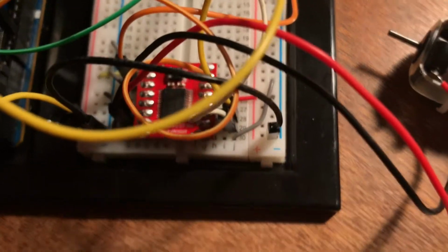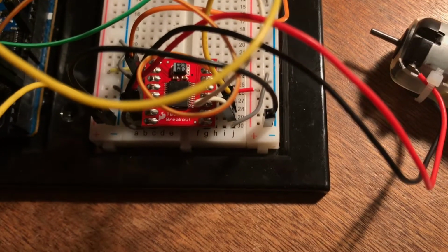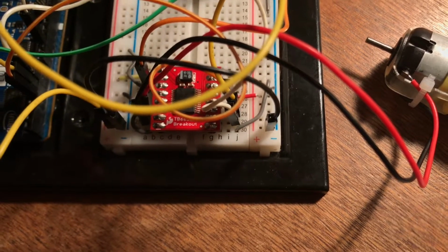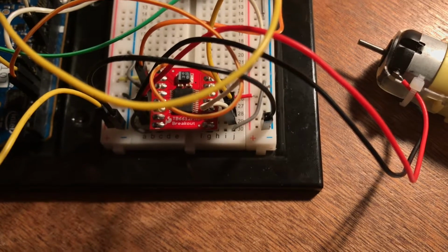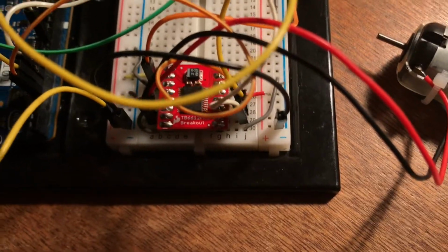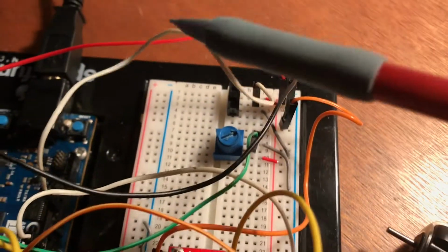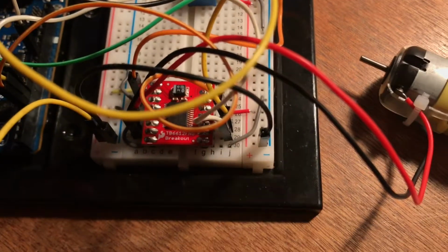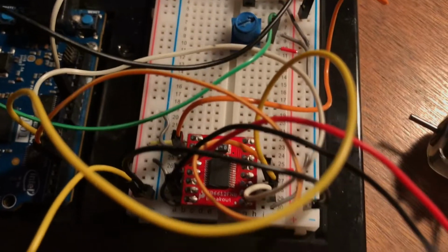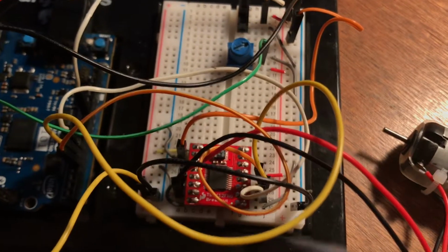Then we go to the other side. We have this red cable here that is attaching the STBY, which is the standby pin, high for the board on and low for the board off, to 3.3 volts, again through this red wire to 3.3 volts. And then the orange wire, it's hard to see, where is it? The orange wire here